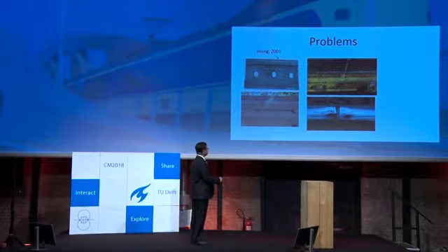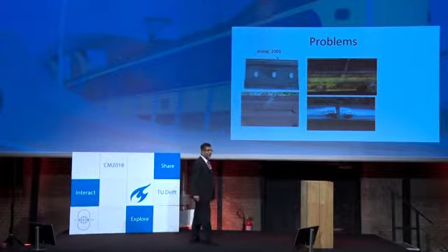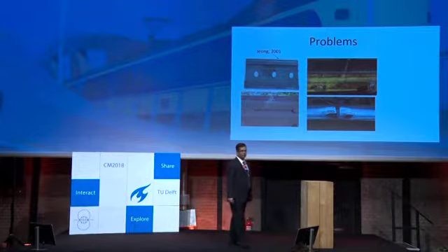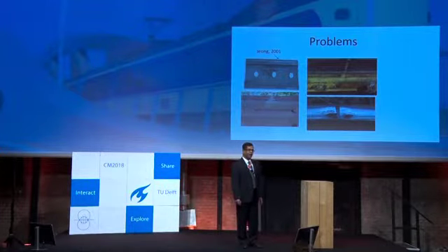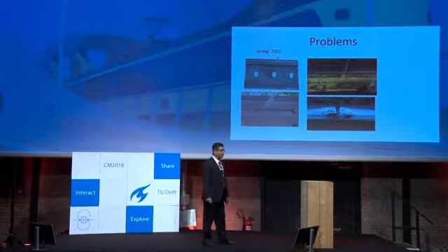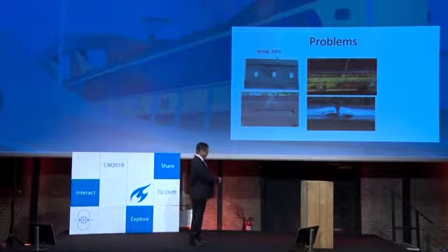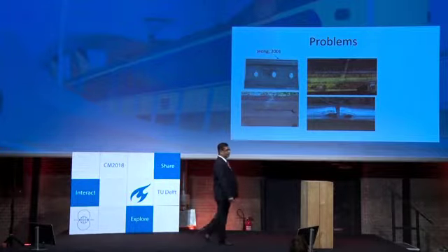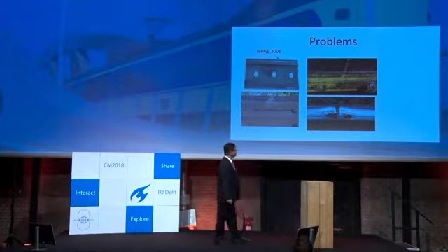You can see the separation from one rail to another by the end post, because this is for isolation. It isolates this section from another section, called a signaling block. This signaling block is useful for the people in the control room, and they can identify where the train is moving. If a train is here, that block is red, and another train cannot come into the block. That is the purpose of the signaling block.